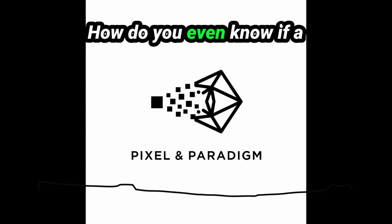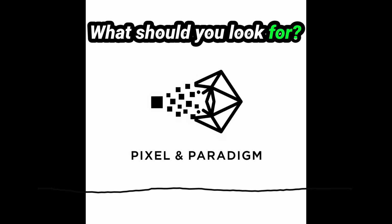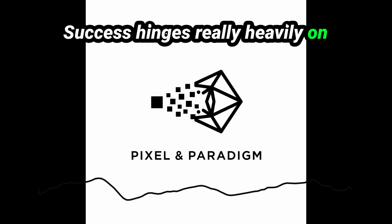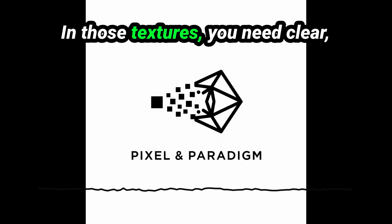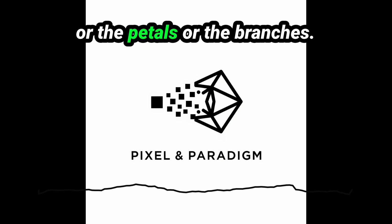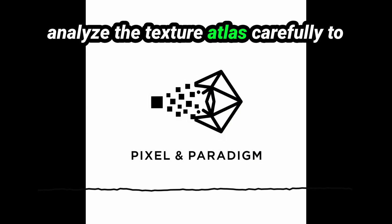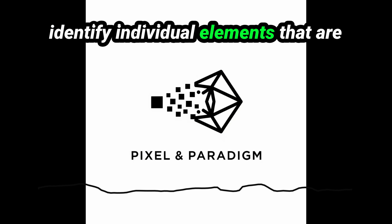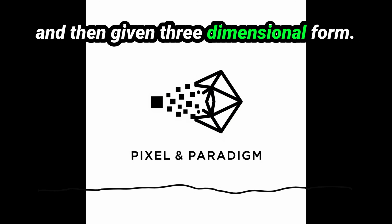How do you even know if a legacy 2D asset is a good candidate for conversion? What should you look for? Success hinges really heavily on the quality of the source textures, specifically the alpha channel in those textures. You need clear, well-defined shapes for the leaves or the petals or the branches within that alpha map. You have to analyze the texture atlas carefully to identify individual elements that are distinct enough to be logically separated and then given three-dimensional form.